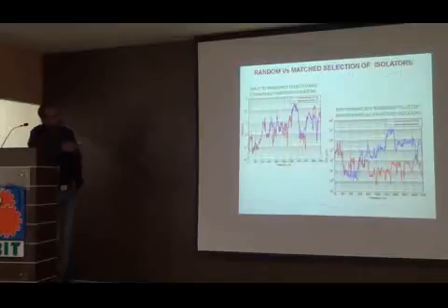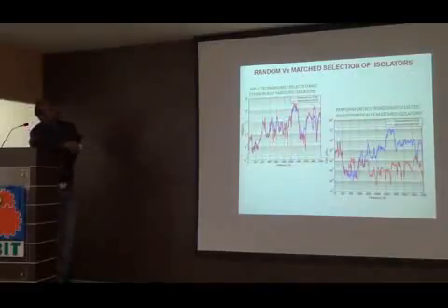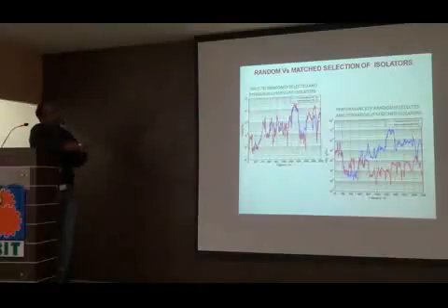And while selecting isolators, suppose you have a bunch of isolators, you should select from them what we call dynamically matched isolators. Dynamically matched means you have to test the isolators and they should have the same natural frequency, and then you should use such isolators rather than selecting arbitrarily. If you take them arbitrarily, they may not isolate effectively.